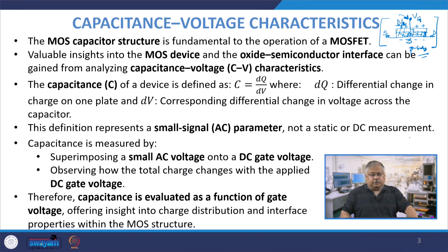That is also one of the advantages of a MOS device, that once you allow the MOS device to work as a capacitor, you do not have to put a passive capacitor in the network which takes more than enough area on silicon. So, a MOSFET can be used as a resistor, we have already discussed that point. A MOSFET can also be used as a capacitor. So, this is one of the examples of that.